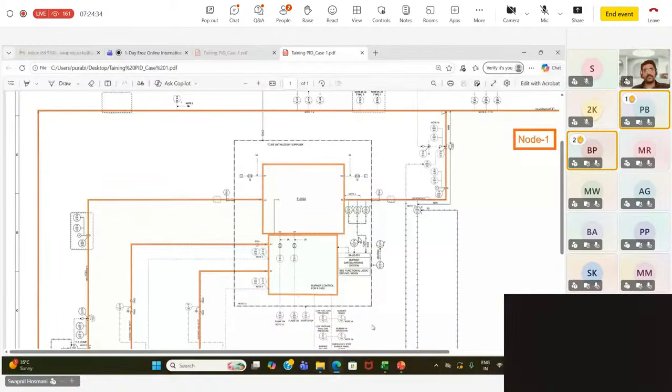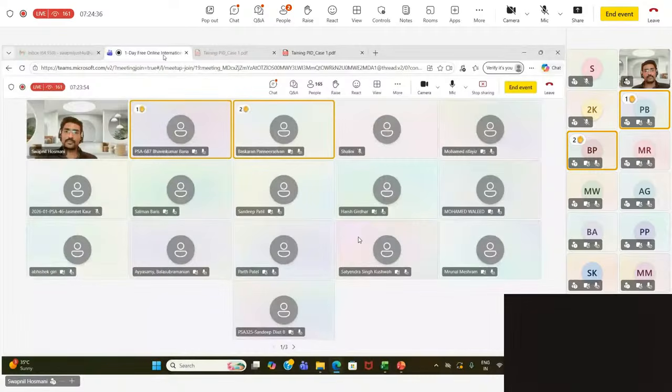Fine? Because they have considered SIL3. If it was not SIL3, then there would be certain concerns. Say if they had considered SIL2, then we would have to relook at it as a design part. But now the burner management vendor, based on his typical design, has considered SIL3.